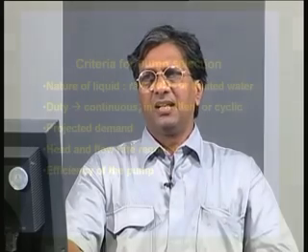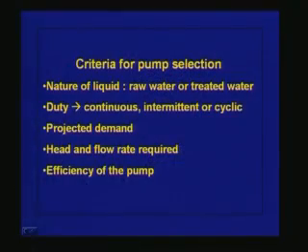This selection of the type of pump depends upon the nature of the liquid, whether we are pumping raw water or treated water, whether we are pumping water for a water supply scheme or a wastewater collection scheme. If we are pumping in a wastewater collection scheme, then we have to ask whether it is meant for pumping sanitary sewage or storm sewage.